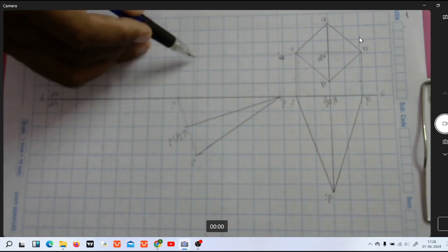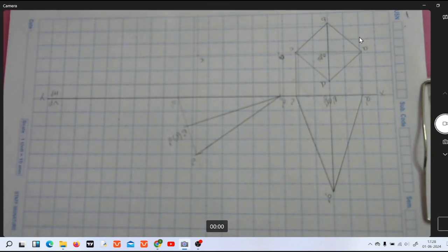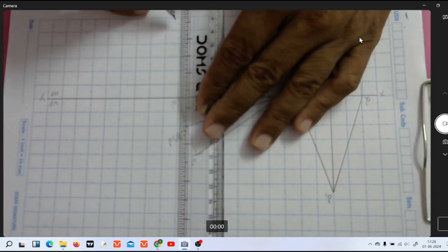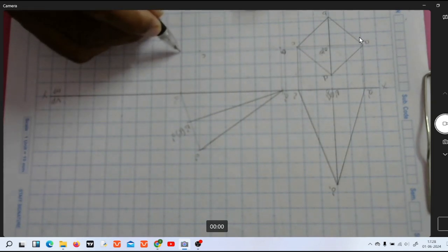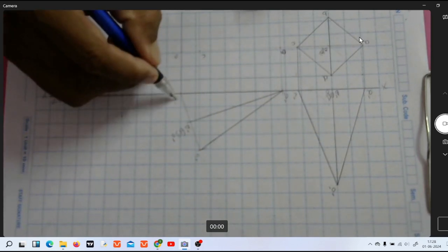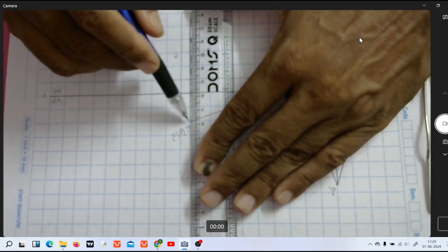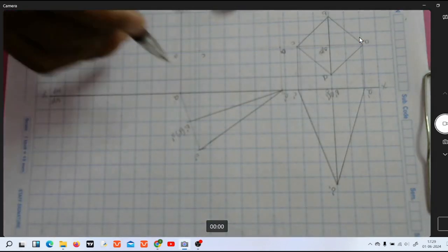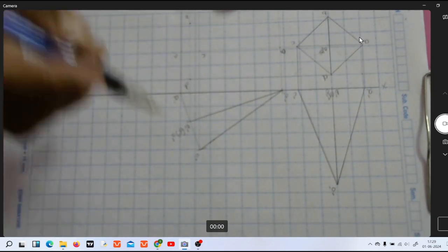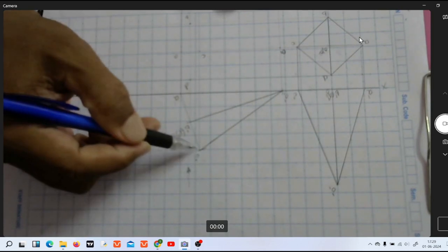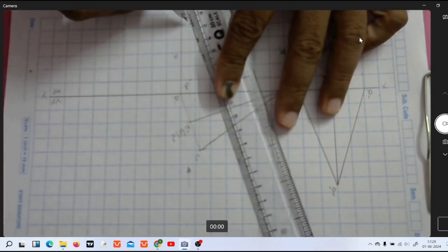Now I drew a line here related to C dash, let us mark it as C. Similarly, now drop down the points from point A dash, you just observe, you got a reference here, this point is A. Similarly, you drop down from point B, now here you got point B, and here you got point D. So when you are looking from the top, this entire base surface is visible. So now let us connect all these points with the help of straight lines.